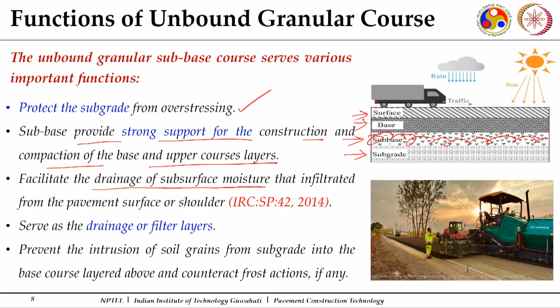Whatever water, through any means, we will discuss what possibilities, if it enters into the pavement structure, it has to be taken out of the pavement structure, and that purpose is served by your unbound granular courses. So, this is a major function, and it serves as a drainage layer and a filter layer. We normally mention names such as drainage layer, filter layer, separation layer. A separation layer can be between a subbase and a subgrade, so that it separates the two materials. The fines of your subgrade should not penetrate into the coarser aggregate structure of your subbase courses. That can be done using a separation layer.